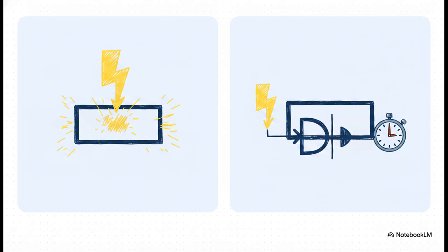A synchronous reset, on the other hand, sees that 0 but patiently waits for the very next positive clock edge to arrive before it acts to clear the output. And this synchronous behavior actually forces the compiler to generate a circuit with an extra AND gate built right into it, taking up physical real estate on the silicon just to manage that strict clock dependence.